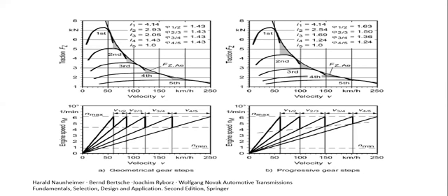When you need 8 or more gears, the solution is the main gearbox with splitter or range change unit, and geometrical gear step or small progression in gear steps. When you need 12 gears or more, the solution is main gearbox, splitter, and range change unit with geometrical gear steps.